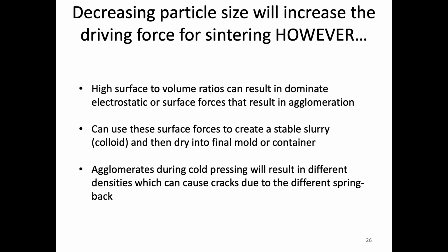You're trying to remove the fact that you have all these discrete ceramic particles with a lot of surface area, and we're trying to sinter them, bond them together, form grain boundaries so that we eliminate all of those free surfaces and instead bond and form grain boundaries. And then remove those grain boundaries and try to get as close to a single crystal as possible. So that's the driving force.